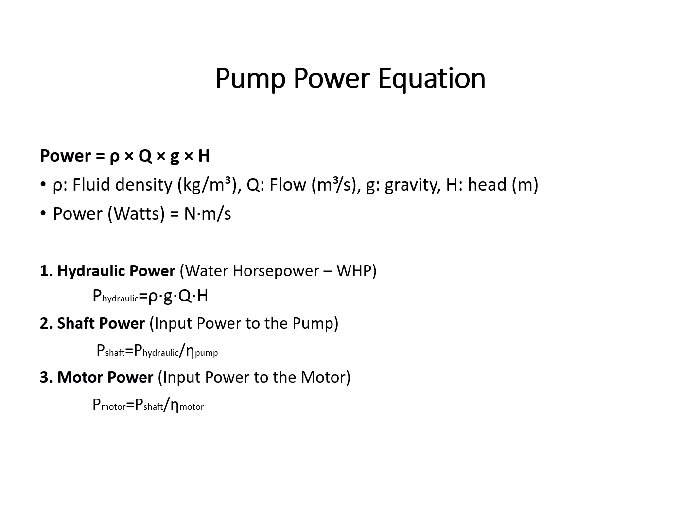Just the power to move the fluid without losses, as if there is no friction, as if there are smooth surfaces, big pipes, short lengths, no friction losses. In this case, we use the hydraulic power, and it is simply the density of the fluid times g times Q times H that will get you the hydraulic power.